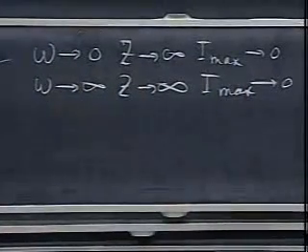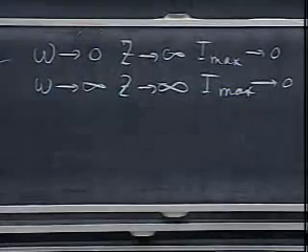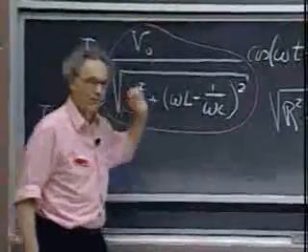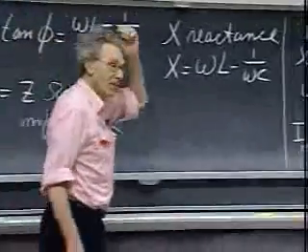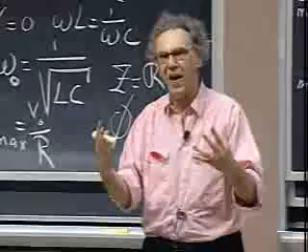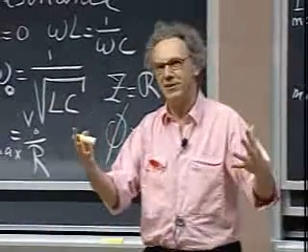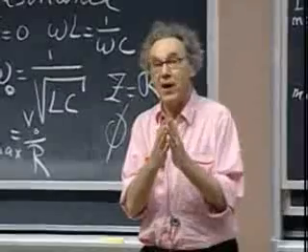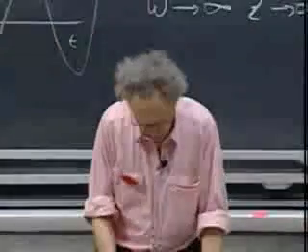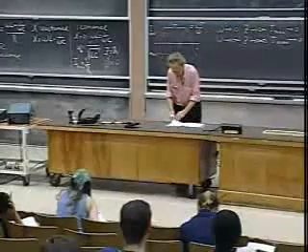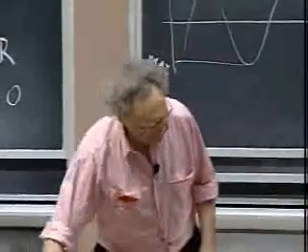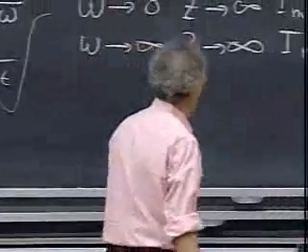And the one responsible for that is the self-inductor. Because when omega goes to infinity, again Z goes to infinity. So again you get 0 here. And that's also intuitively pleasing. Because if you have an infinitely high frequency, that means the self-inductance puts up an enormous fight. That's ideal for a self-inductor, to fight currents if the time over which the changes occur goes to 0. And so then again, it says, sorry, you can't have any current. So that's also intuitively pleasing, that the self-inductance then becomes the dominant factor. And so what I can do now, I can plot the Imax as a function of omega.